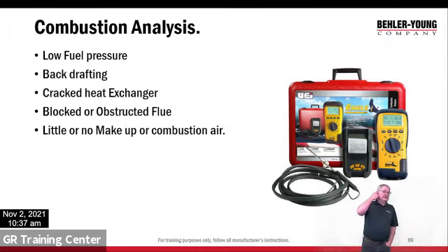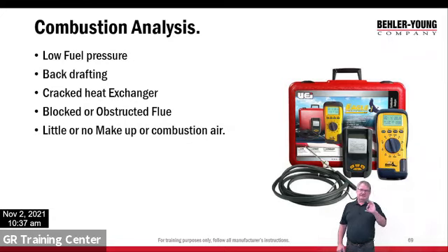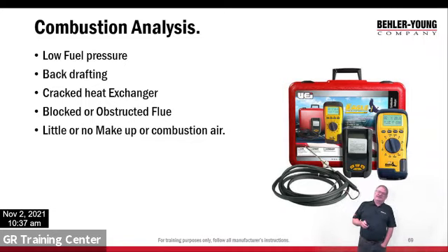So combustion analysis is going to tell us, is our fuel pressure too low? Are we venting properly? Are my heat exchangers cracked? We haven't even gotten to heat exchangers yet. We're going to talk about a cracked heat exchanger because generally a heat exchanger is going to pull air in. So we can screw up the whole combustion with a cracked heat exchanger. Blocked or obstructed flue. What if my chimney's not venting properly? What if I don't have enough combustion air in that little space? We're going to mess up our combustion. So low or no makeup air for combustion, we'll also be able to see that from this little test.